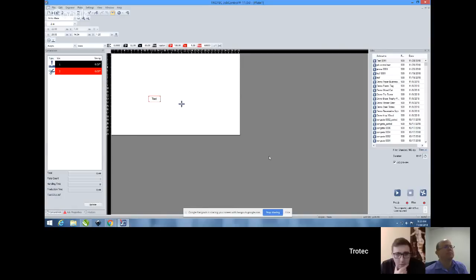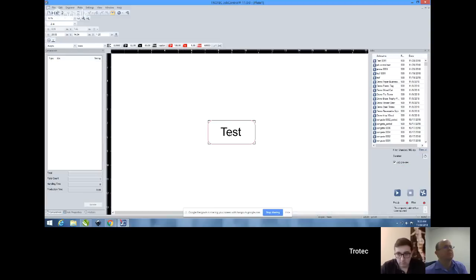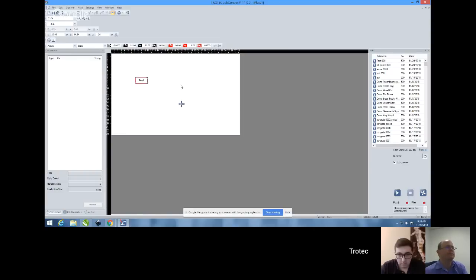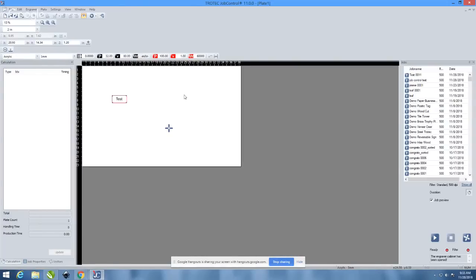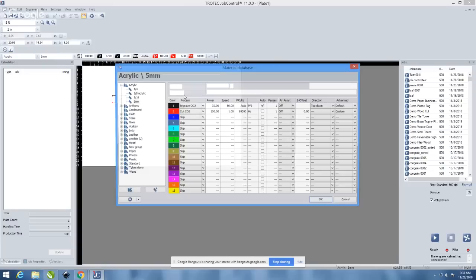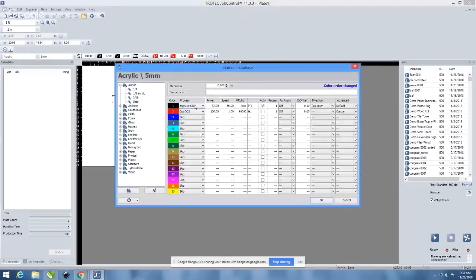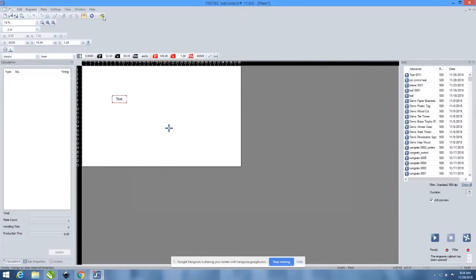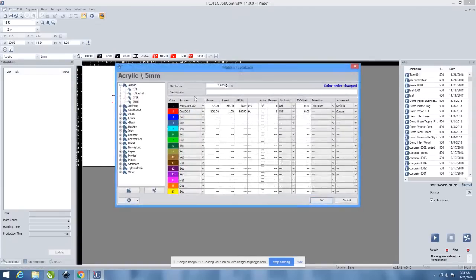Okay. Anthony, what do we have next? Yeah, so up next, we're going to be talking about material settings. Let's jump into our material settings. So we have our file here on our working area. We'll want to assign some properties to these lines and these texts so the laser knows what to do with them. So if you are using some of the materials that you bought from Trotec, you should be able to select them in your material database, which you can find by double-clicking your working area. Again, that's double-clicking the working area, and your material database should show up. There's also an icon at the top here. You can click that to bring up the same screen.